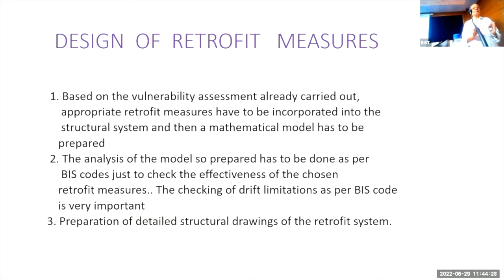Now, once it is identified, critically analyzed, and location of the vulnerability is identified, there are two aspects of identifying the location of vulnerability in my structural elements. Some of them may be local and some may lead to the global failing of the structure. That understanding has to be there. Based on that, we have to prepare a mathematical model. And in the mathematical model, we fit our retrofit element. It is required. And after that, I am coming almost to the end of this.